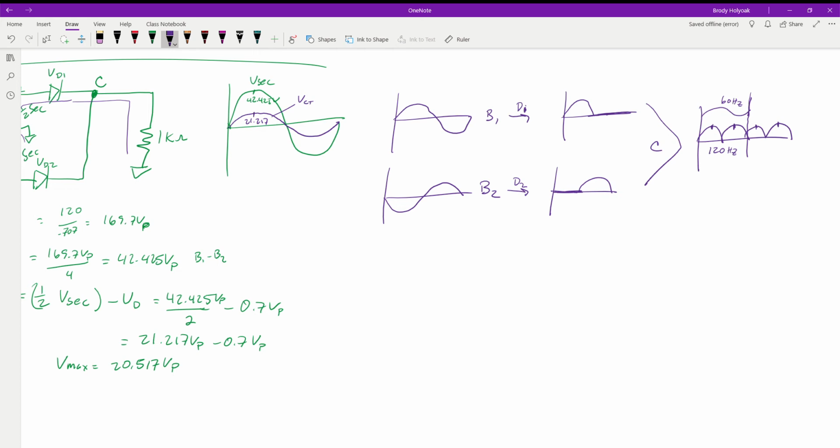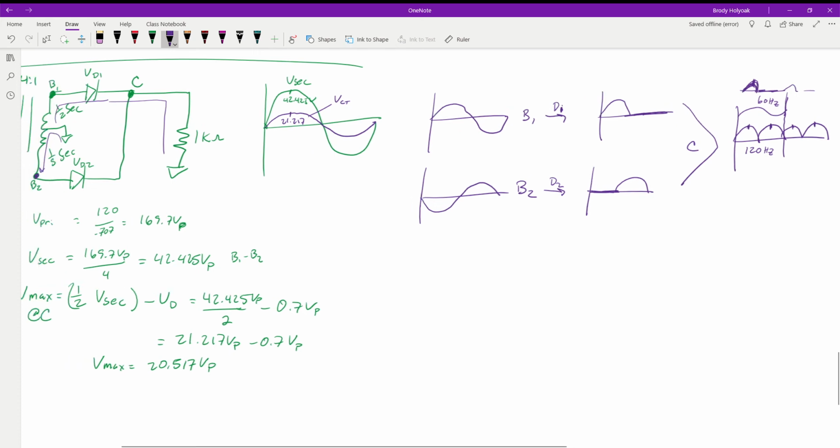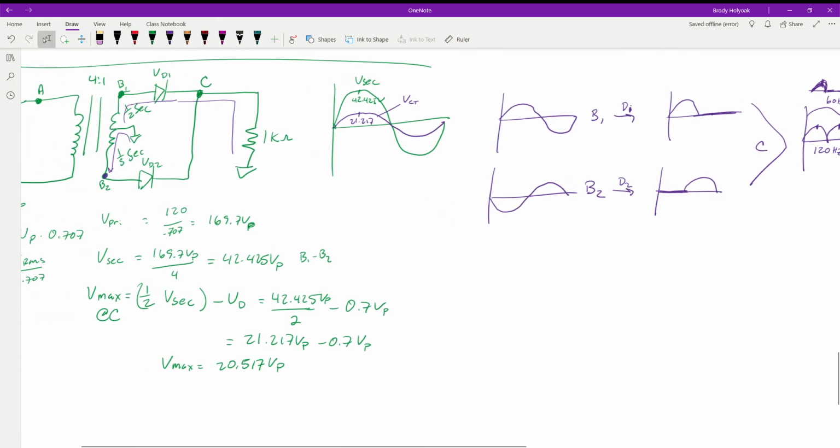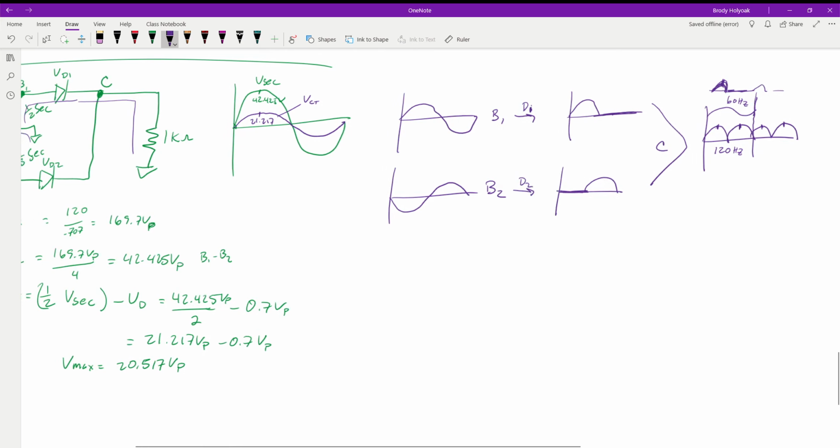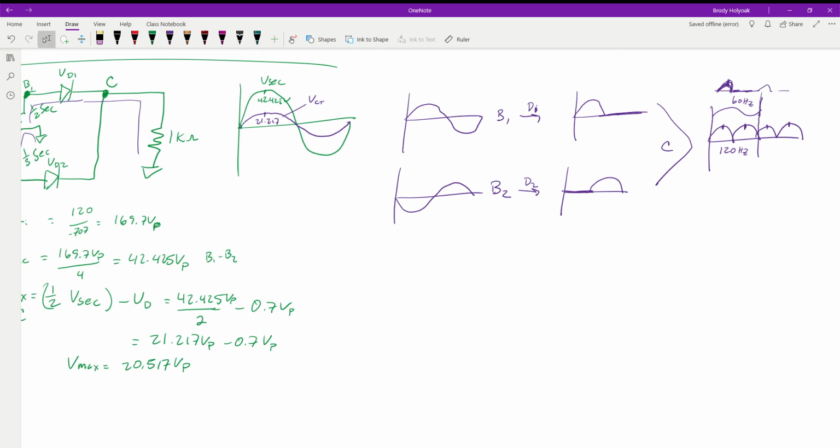But just understand that with a half wave rectifier, we had just the one hump and then nothing in the same amount of time. So we had one positive peak and then wait, and one positive peak and then wait. But when we do it this way, because we've inverted the signal and clipped off the negative ends of our signal, we end up with two positive peaks in the same amount of time. So we've doubled our frequency. And like I said, that's going to be important when we get to the filtered stuff. So with that, we have these two humps, and this is why it's called a full wave rectifier versus a half wave, because now we have the full signal being inverted and flipped and adjusted to where we can actually use it.